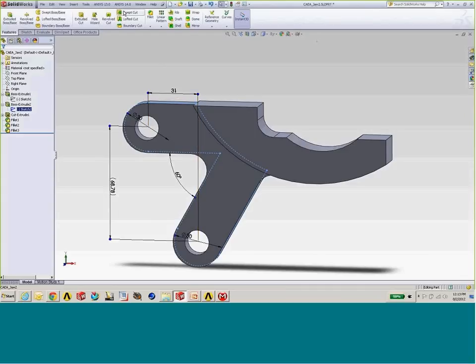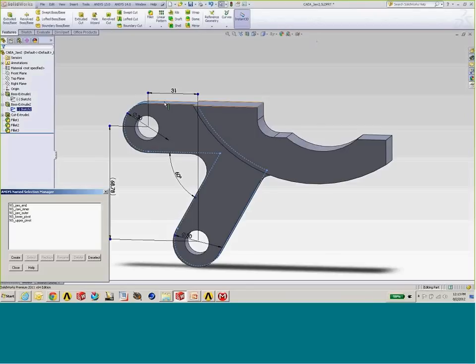In your CAD tool, you have available to you the name selection toolbar from the pull-down menu. With the selection toolbar at the CAD level, we can define geometric entities like surfaces or edges or bodies that we want to have a name assigned to when we bring this geometry into the Workbench environment. These name selections can also be defined downstream, either in Design Modeler or in the mechanical tool. But if you're comfortable with the CAD side and you like to do as much work as possible in the CAD tool, you can use the name selection manager at this level, and these name selections will propagate through the process.